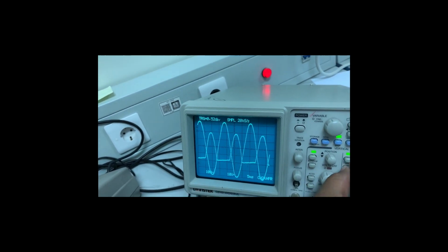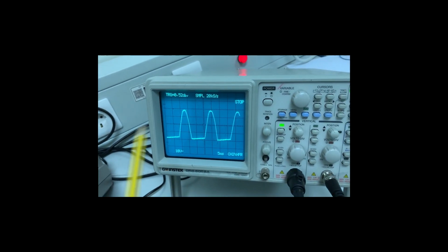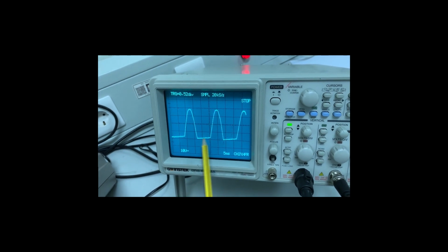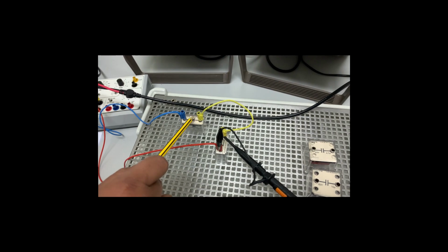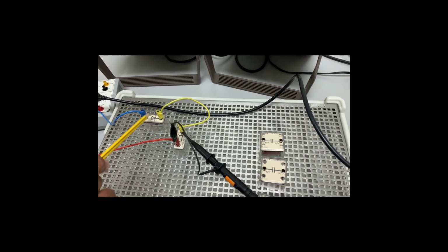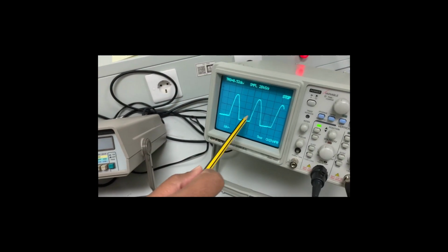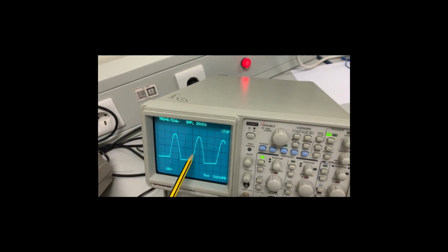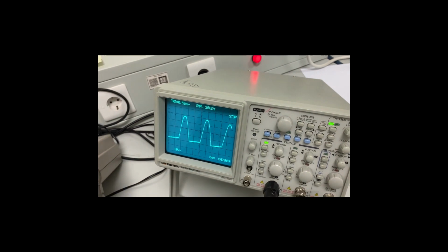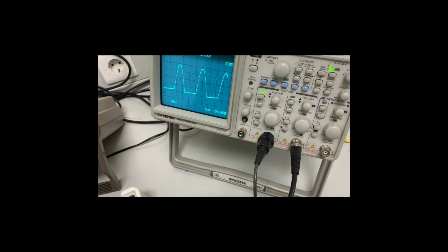So set this. So what is this? This is a half wave, the positive half wave, and the negative half part is clipped off. Why? Because there is one diode here, which means it is working only in the forward bias condition. When there is a negative voltage, it goes into reverse bias, and then the negative part is clipped off. So this is a half wave rectifier circuit. This is without the capacitor. When I add the capacitor to it, the effect will change.